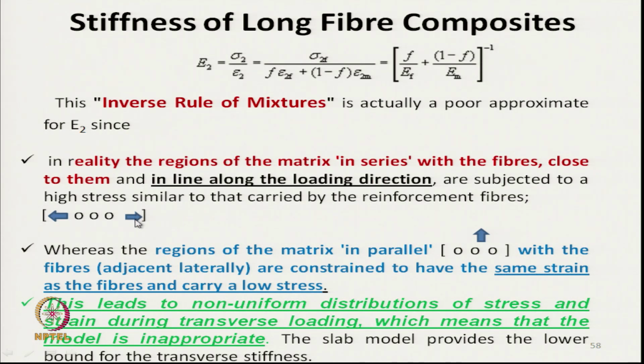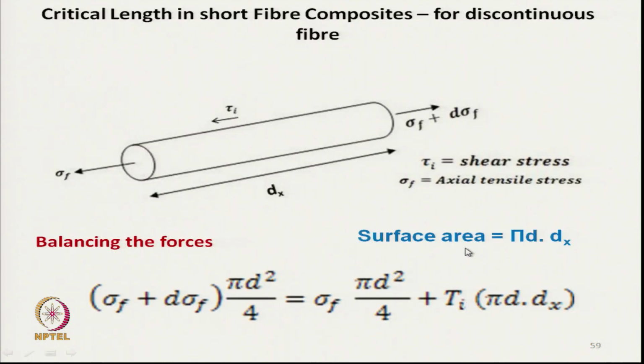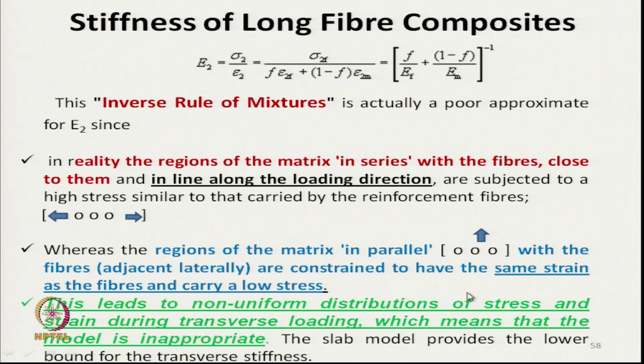But in other places where the regions of matrix are in parallel, when the loading is in this direction, what will happen? The majority of the load will be carried by the reinforcing material. So, the load on matrix in between this reinforcing zone will be low.